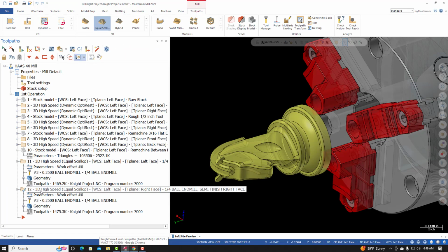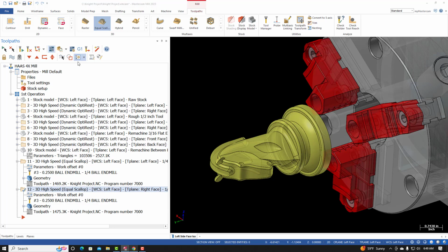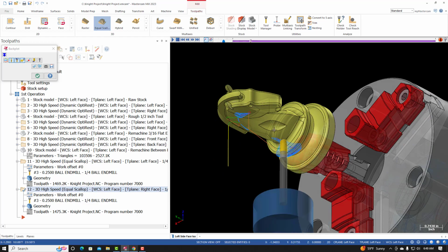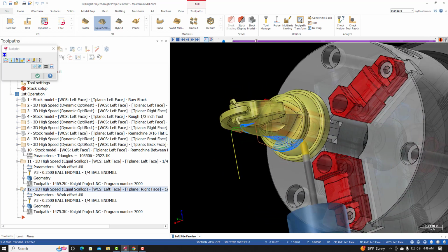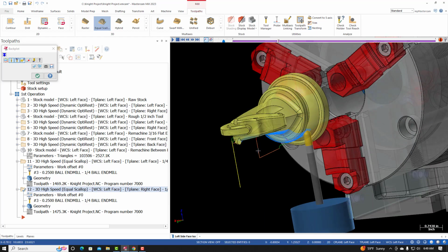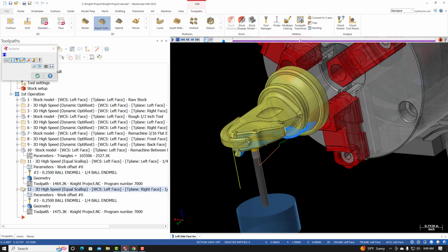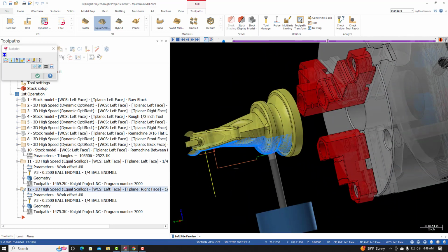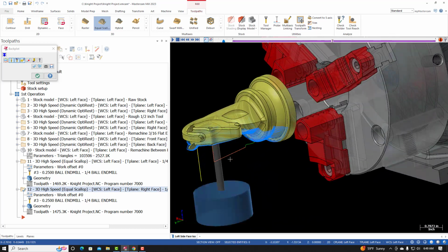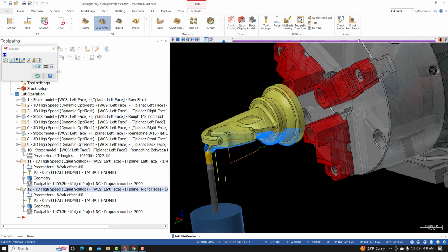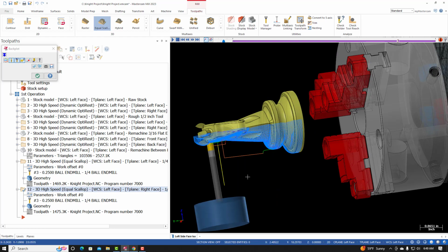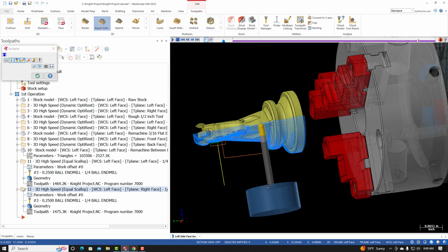So from here, the toolpath is now done regenerating, so I will run just the right side semi-finish toolpath in backplot. And it's a mirrored image of what the left side toolpath looks like. This part is symmetric. We're using the same geometry. So if you were to compare these 2 toolpaths, it is pretty much a mirrored image of the left side semi-finish toolpath. And it looks like it's a pretty efficient toolpath. It's keeping the tool down for the majority of the toolpath.